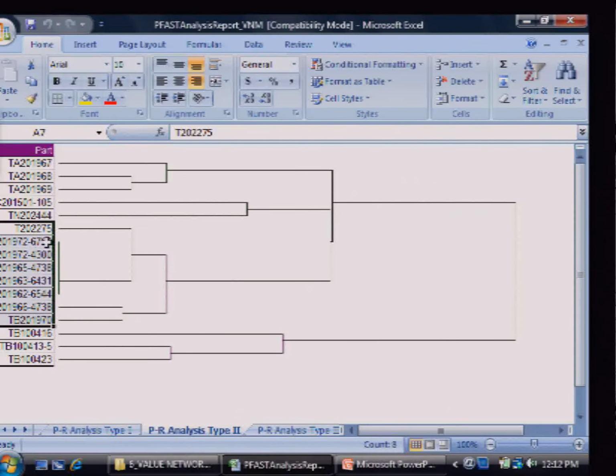So yes, the work centers used to make this identical family of parts are not going to be sufficient, but if you added a couple more work centers, you could also make this part and all these parts, and that's why you can see in this dendrogram that this is what is called a flexible family of parts. So it's not a value stream which is identical, but these are highly similar value streams.